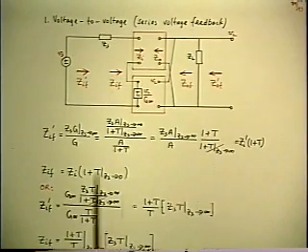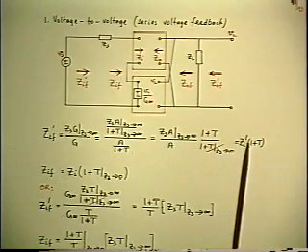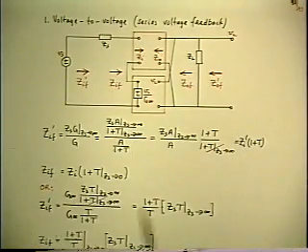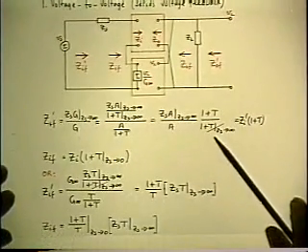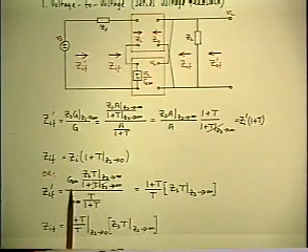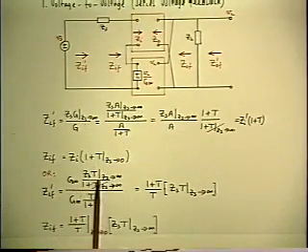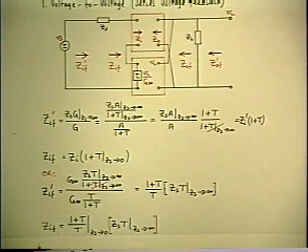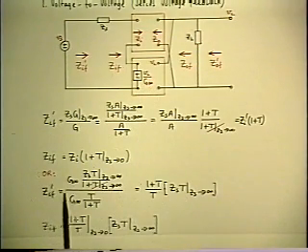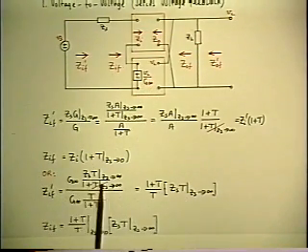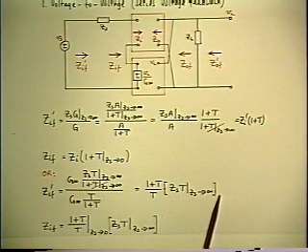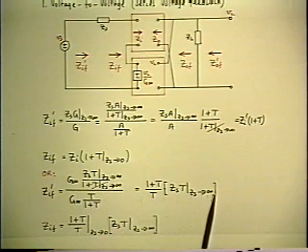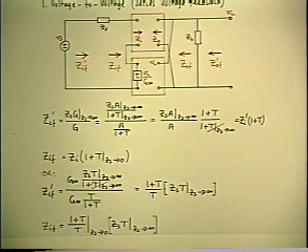However, who cares about what the open loop values were anyway? So make the other substitution, which is go back to the first line and substitute G with G infinity times D. G infinity cancels because Zs is not inside G infinity either. Separate the other terms to find the limits, and this is the result you get, which says the input impedance with feedback is determined solely by the loop gain.